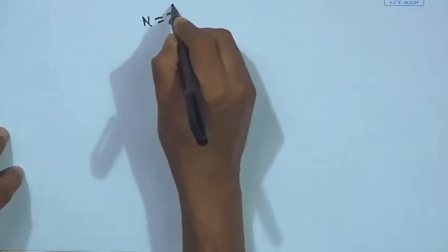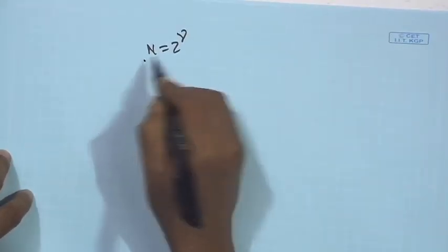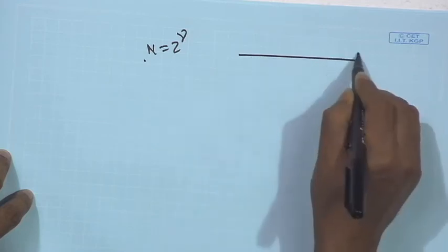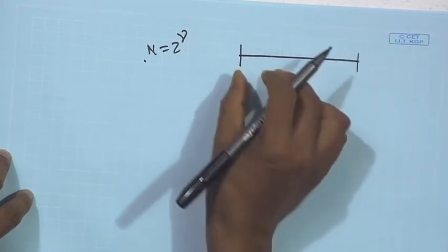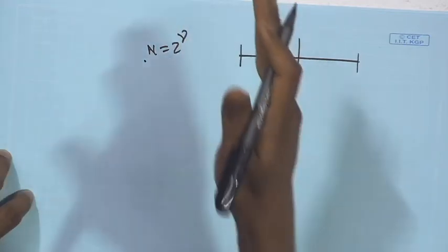Yes. So, what they did in the FFT radix 2 algorithm is, if N can be represented by 2 to the power something, the restriction on the length of the DFT is that I want to divide the whole signal in binary fashion, into 2 parts, then 4 parts, and so on.